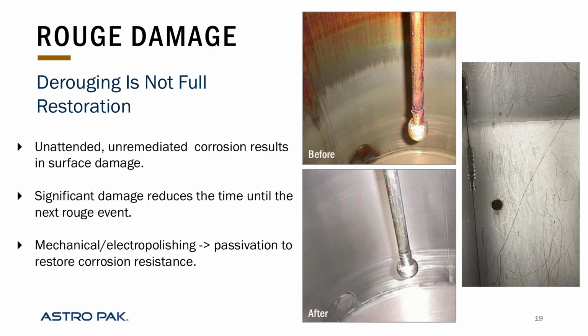So I definitely recommend, if you have a profilometer, to start using other metrics to identify scratches. I think for acceptance testing, RA is a very comprehensive measurement. And for inspection and maintenance, that's when you can start to adopt some other ones, because it turned out that mechanical damage on this order was enough to cause corrosion, whereas the 1,000 ppm bleach was completely compatible with the rest of the surface, or the surface as they purchased it.